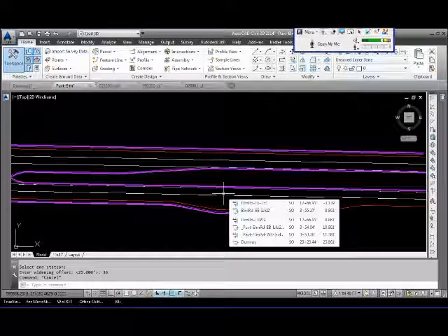Now, one thing to note about this pavement file is that all of these offset alignments are actually sourced within this file. They're not anywhere else. They're physically in this one file. The reference line alignments are not in this file, but just the offset alignments, horizontal geometry, that type of stuff. That reduces the synchronization when you go to reference it into another drawing. Everything is sourced here. You have one source. You don't have to make a design change somewhere else and chase it on through.